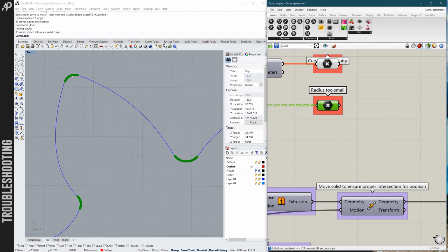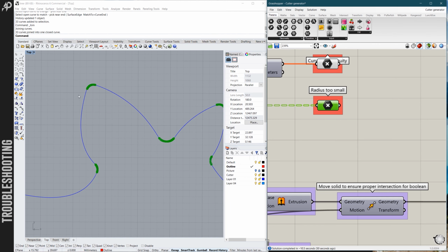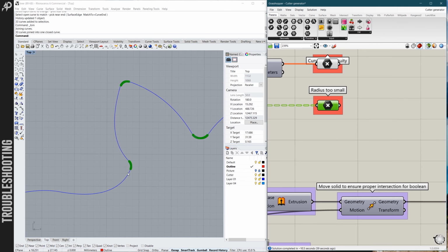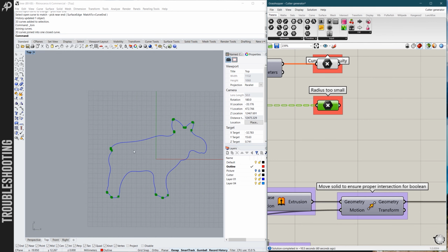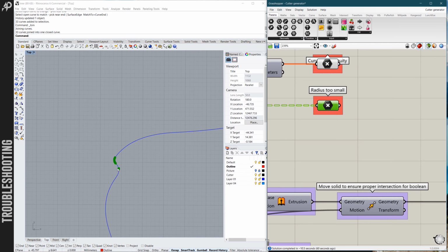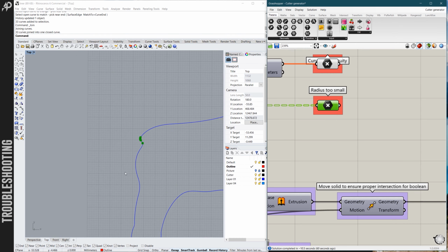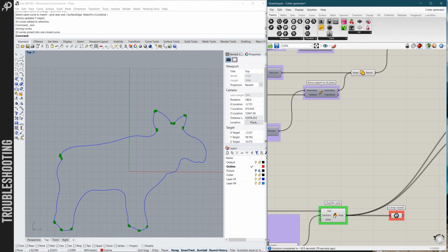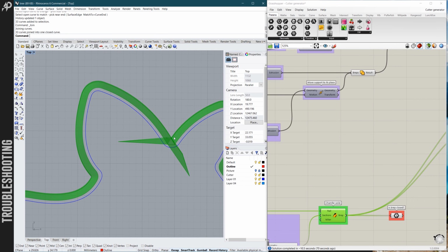You do not care about the outer corners, because you are sweeping on the outer rail, you're offsetting the initial curve outward, so the outer corners will always be okay. The deviations only happen in the inner corners, so we basically have 3, maybe 4 places where deviation will happen. But we will check that later. For now, there's nothing to check because our BREP is still broken.